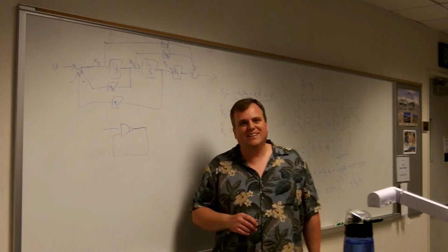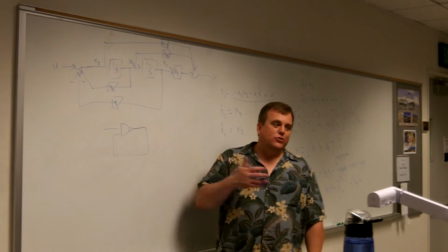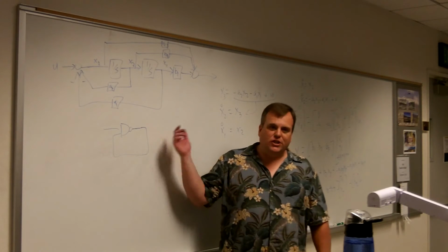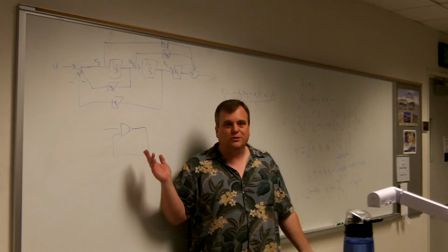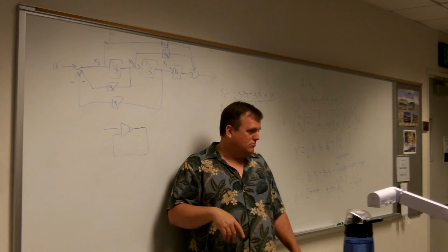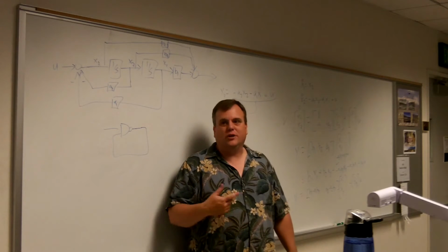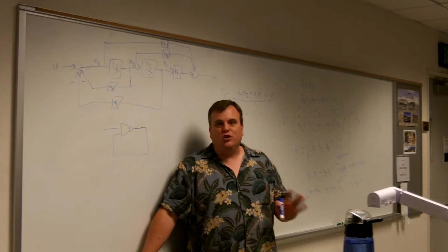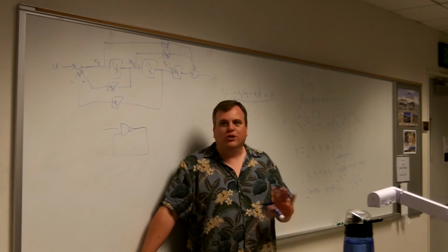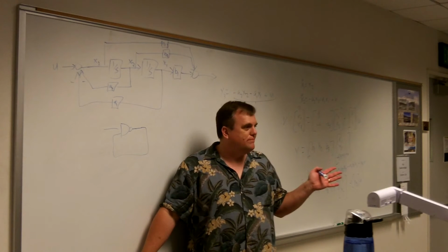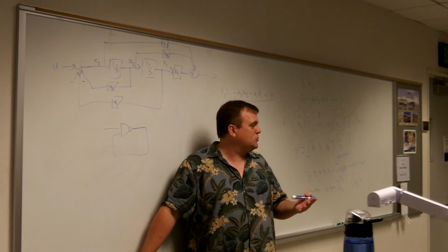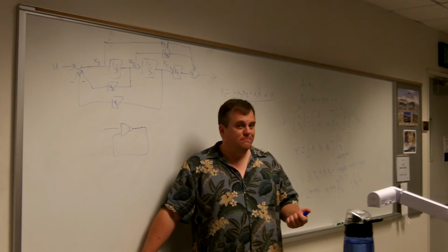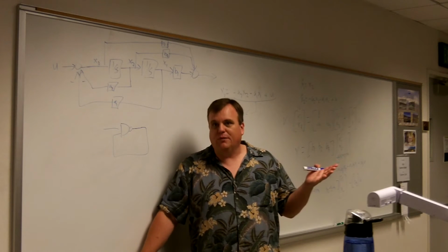You can actually prove them. You can actually take the transform equivalent of the Laplace transform called the Z transform. You can take the Z transform of those equations that we got for the system when you start writing your state diagrams, and you will get expressions like this, and you can actually check to see whether it's stable or not, and how the transitions work and everything else. Believe it or not, this is no different than what you learned a year or 2 ago. This is just being done in a much more general sense, and I'm proving it a little more rigorously this time. But it is really the same thing.